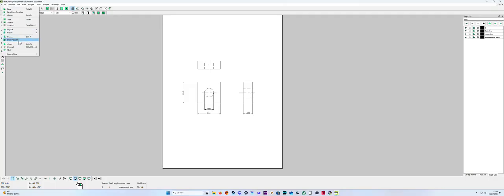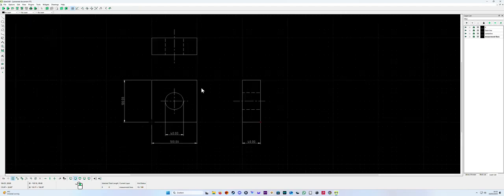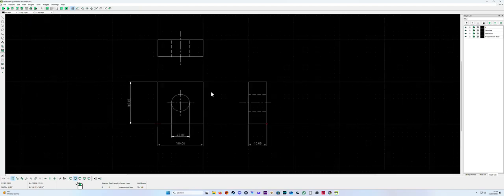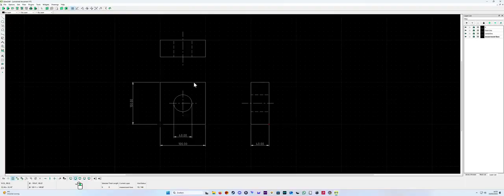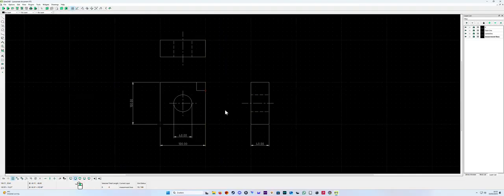So here you go back from print preview to the drawing. So let's put some more things on it. Now I'm gonna take a little corner away here. Let's go here to top, pick the lines, 2 points, and I'm gonna take a small corner away here, like that.